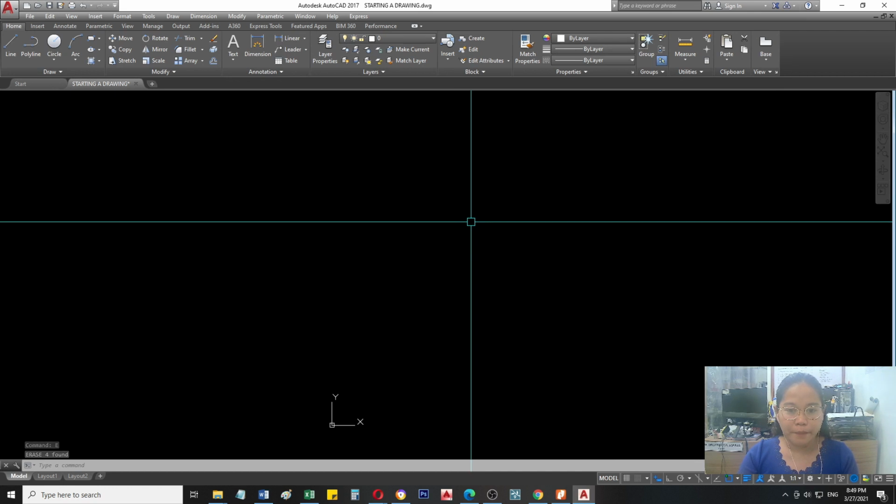Next system is the relative coordinates. In the relative coordinate system, this allows you to enter points in relation to the first point you have entered. So, from the first point, the next points start from there. After you have entered one point, the next to be entered is the X and Y. This means that AutoCAD will draw a line from the first point to another point X units over and Y units up relative to the previous point. So here is an example for that.